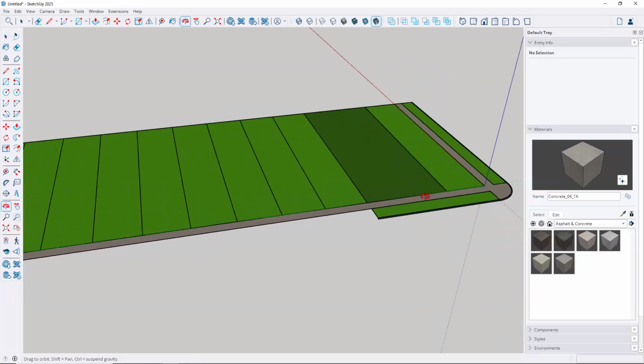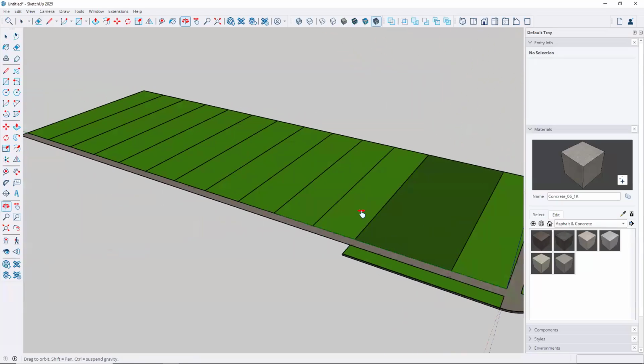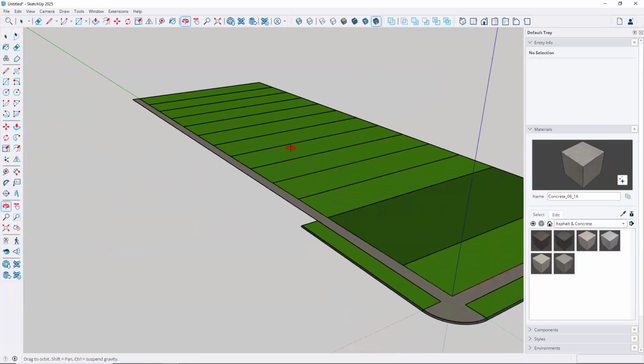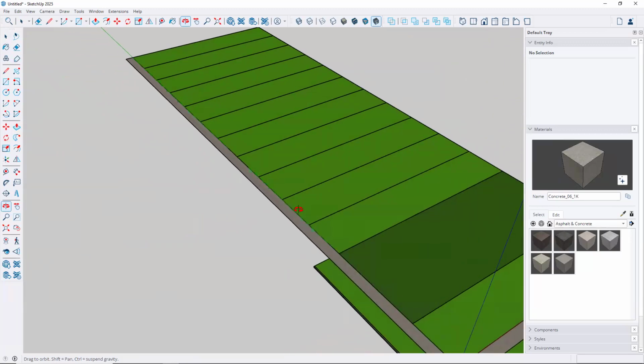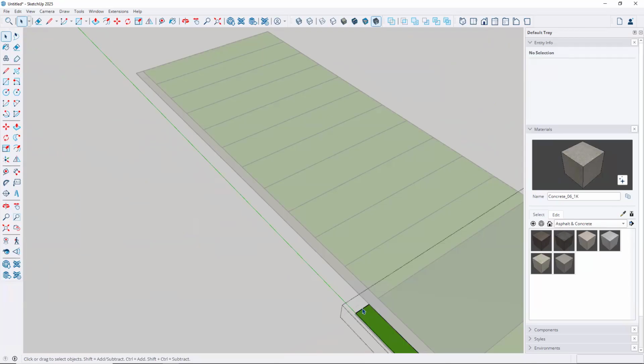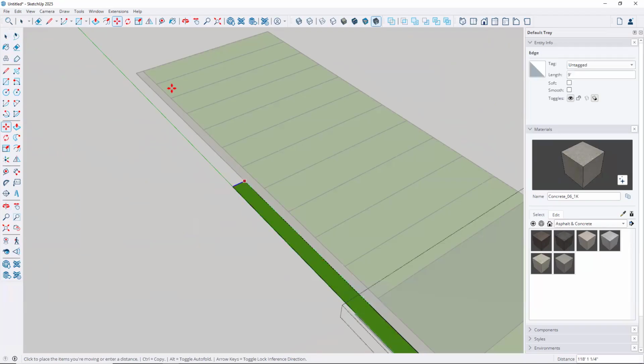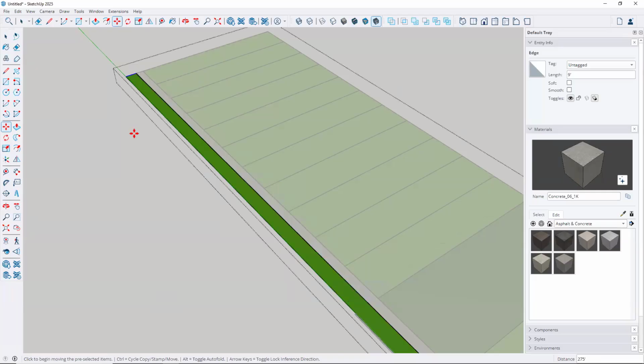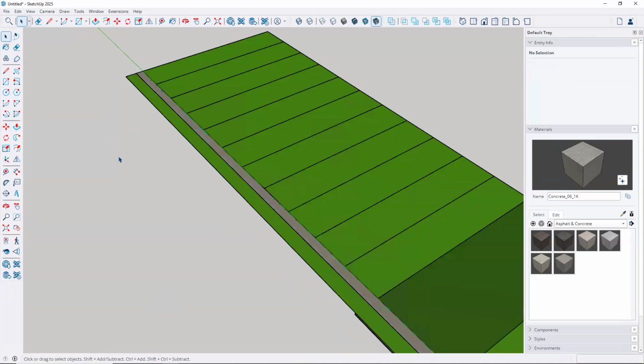Time to extend the parkway. So I'm going to do this. And I want you to get comfortable zooming in, zooming out. And then I'm going to double click the parkway group. I'm going to select this endpoint, type M, move it from this endpoint all the way over to that endpoint. And I know it's just one endpoint. I don't have to worry about an arc and small segments. So I can stay this far out. And when it shows me endpoint, I give it a click. Then I tap the space bar and I click away from that.